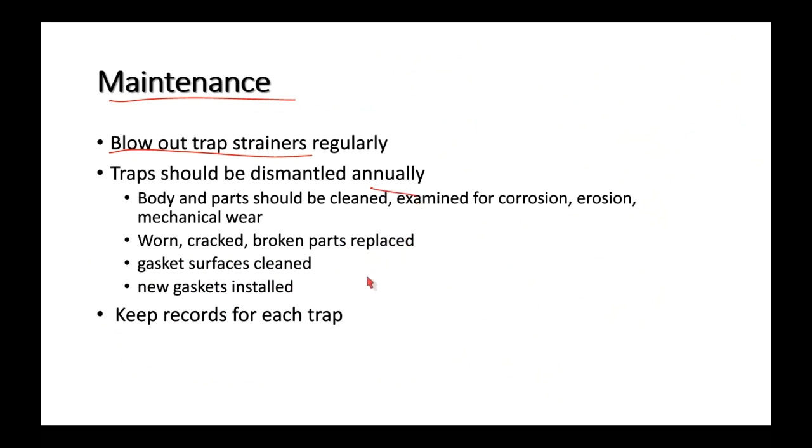And then dismantling annually and repairing. So this is a big thing in many powerhouses. The power engineers, when they're on their maintenance rotation, in the summertime, maybe it's a heating plant, during that period of time, you take apart all of the traps and rebuild them. That's a pretty common thing in many large heating plants, like say SAIT.